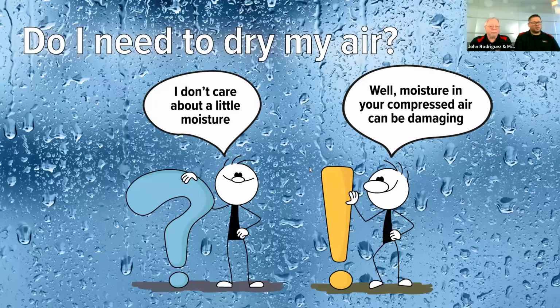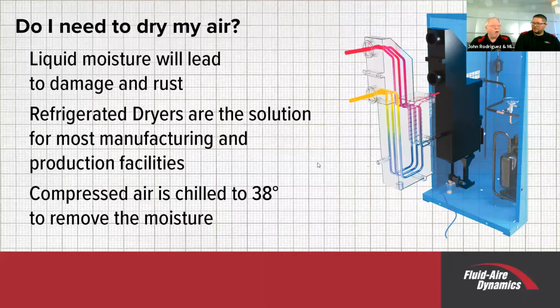So, okay, we found out just how much we need. Do I need to dry my air? I mean, it's just air, right? Yeah, it's just air. But when you take a number of volumes of air and squash it down to a smaller volume, you're adding all that water content to a smaller volume. Not only that, but by compressing it, you heat it up. And heating it up allows that hot air to retain more moisture.